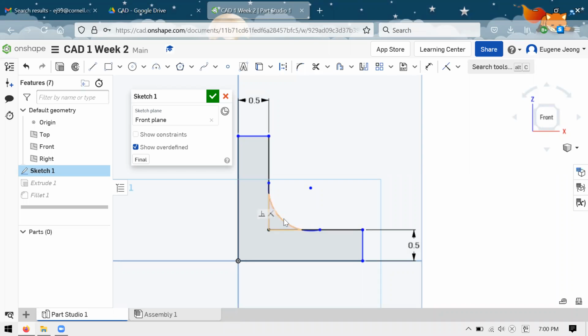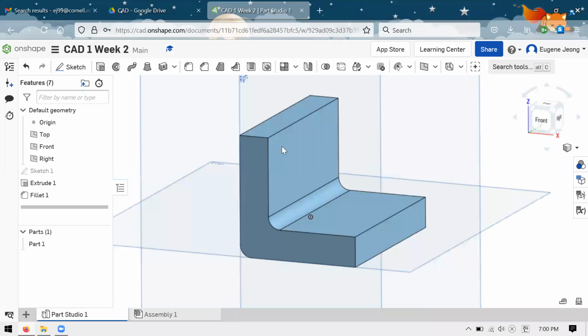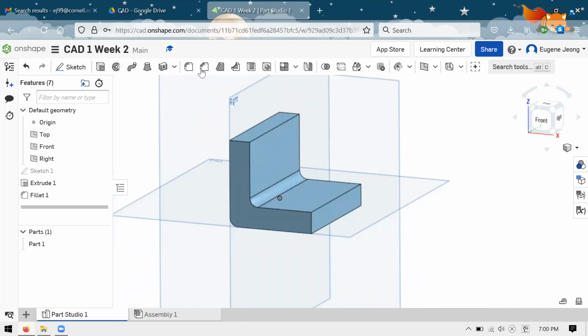Generally, it's best practice not to do this. It really creates more of a headache than you need. So if you're ever in a sketch and you're painstakingly dimensioning this little circle just so you can get this rounded L geometry, just do the 3D fillet in your 3D feature tools. So that's your introduction to these two tools. If you have any questions about that, I'll just pause for a moment.